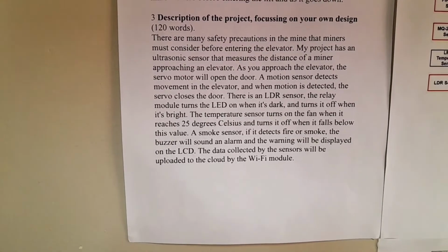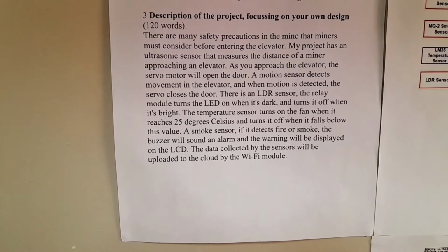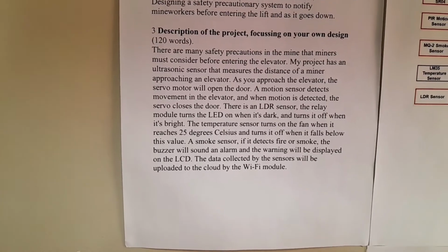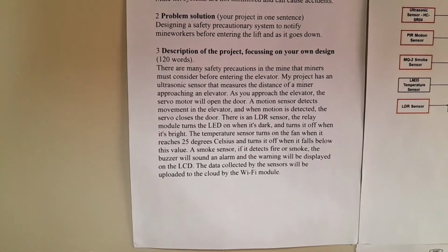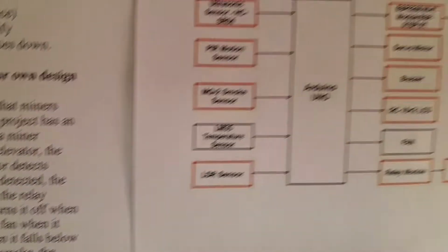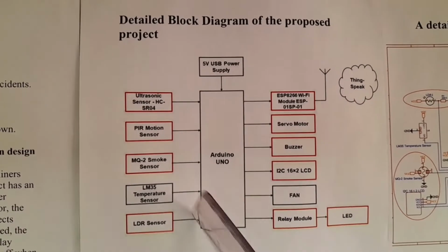And then there's a smoke sensor. If it detects fire or smoke in the lift, the buzzer will sound an alarm and the warning will be displayed on the LCD. And all the data collected by all these sensors will be uploaded to the Wi-Fi module, which is ThingSpeak. Moving forward to the block diagram of the proposed project, we have an Arduino Uno,